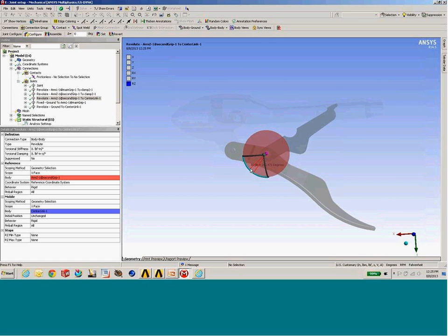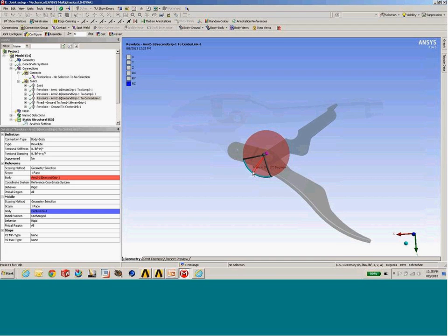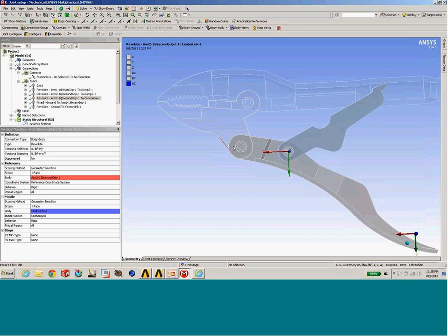This is actually using the solver to figure out the instantaneous position of the parts in this assembly. Okay? It's treating everything as rigid and just doing a kinematics analysis as I adjust this joint setting. Now this configure tool can be used, as I said, to check your various connections and make sure they're all valid. You can also use it to set the initial position of the geometry. So let's say I wanted to open up the wrench and solve it in that position. I can set that to be the actual position, or I can always revert it back to its original location. So you can use that to very quickly and easily figure out how to set those conditions.